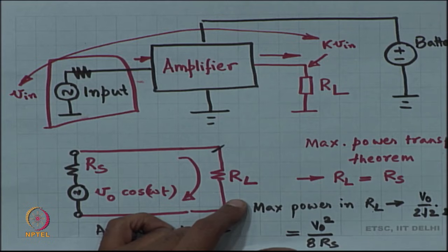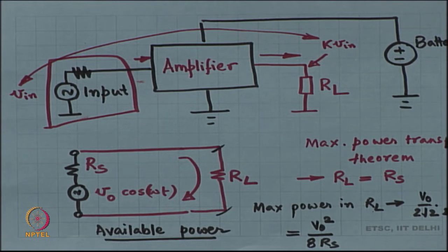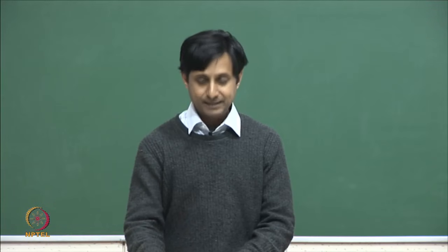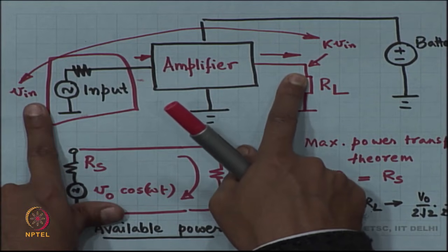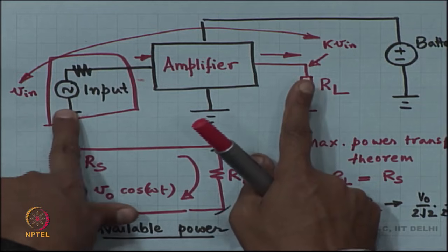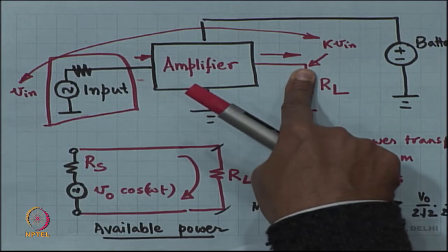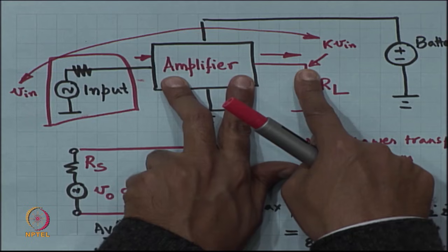So, think about it, I gave you the answer, but think about it. I gave you a compact answer, you might not understand it in the first shot, so rewind, ask yourself again, take clues, take hints from what I just said, that the DC power is never going to be translated into any other frequency. Suppose the frequency is at omega, omega power is going to remain at omega if the circuit is linear.